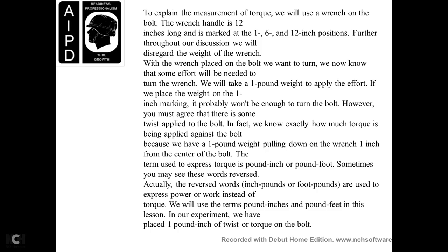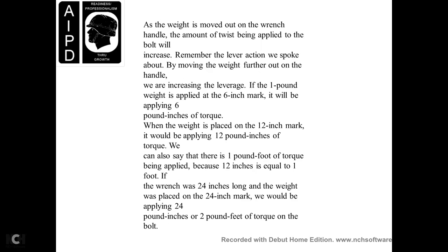In our experiment, we will place 1 pound-inch of twisting torque on the bolt. As we move the weight along the wrench handle, the amount of twisting applied to the bolt will increase. Remember the lever action we spoke about: moving the weight further onto the handle increases the leverage. The 1 pound weight applied at the 6 inch mark will apply 6 pound-inches of torque.